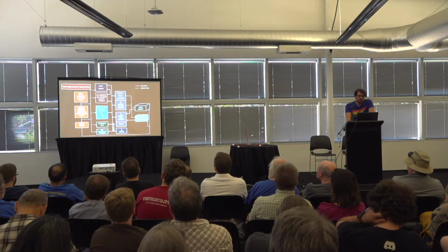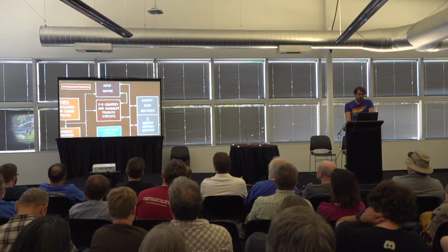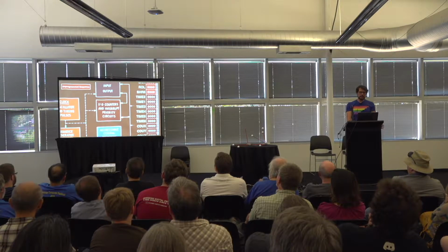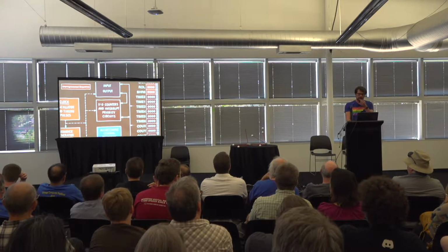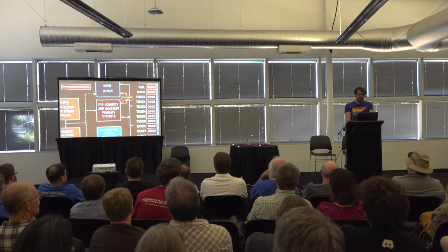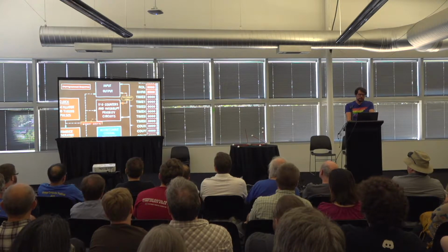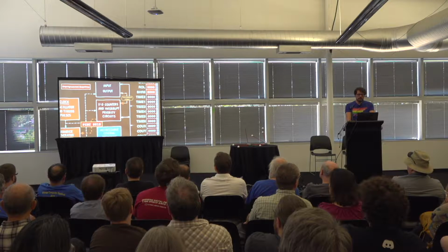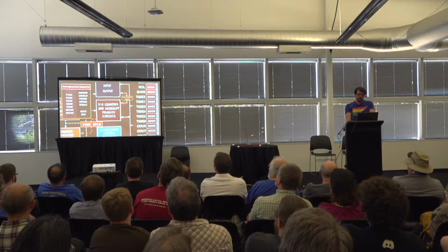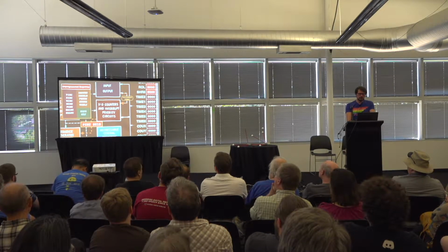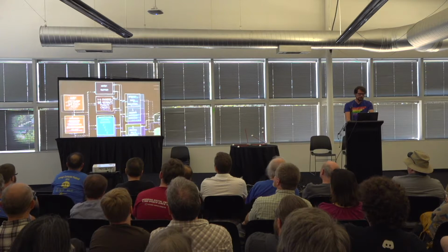But there are more microprograms than the ones for the machine instructions. Since there's only a single adder unit in the whole computer, incrementing and decrementing is done by converting the pulses into special instructions that get injected into the instruction stream. There are 14 of these so-called unprogrammed sequences with their own microprograms. Some count or shift, some are for interacting with debugging hardware, and these control the interrupt and reset sequences.